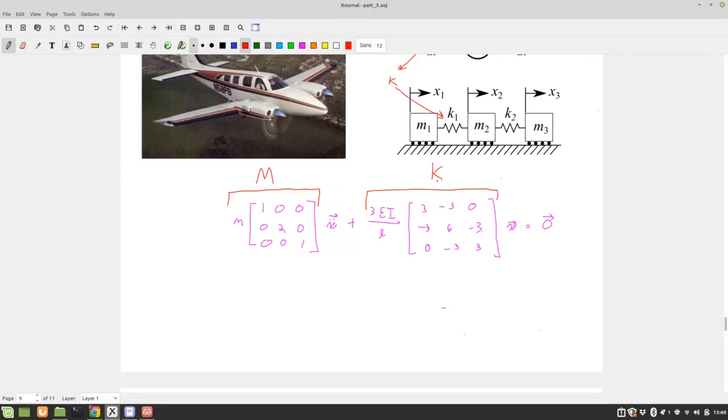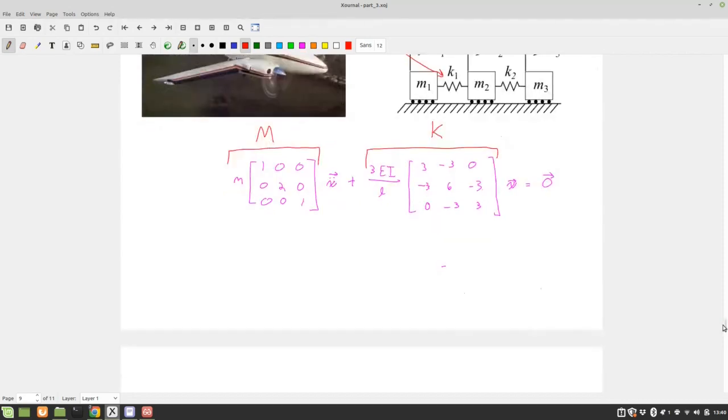All right, so remember there were 2 different ways we could solve for this. 2 different eigenvalue approaches. We talked about it briefly. Anyone remember the 2 approaches? We have a generalized eigenvalue approach where we have K and M in our eigenvalue problem. Or we can use a mass normalized approach, right? And the difference is when we have our mode shapes at the end, if we use a mass normalized approach, we have to multiply by the M inverse matrix, or M inverse square root matrix. So let's start with the mass normalized approach.